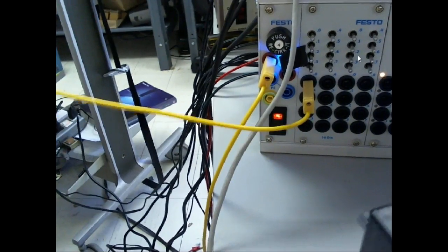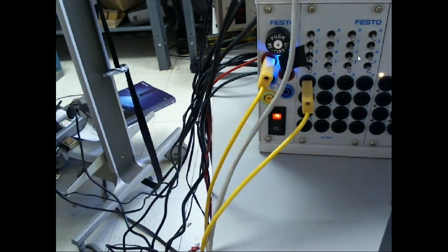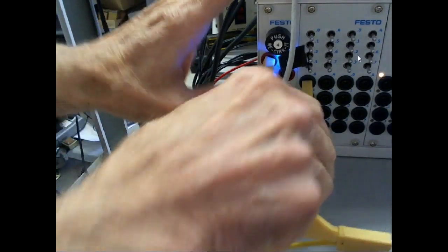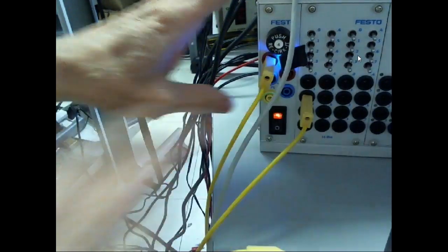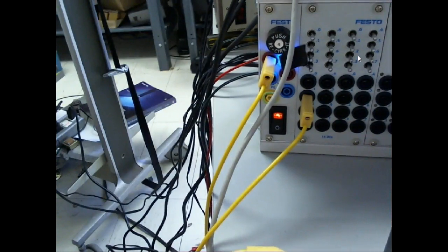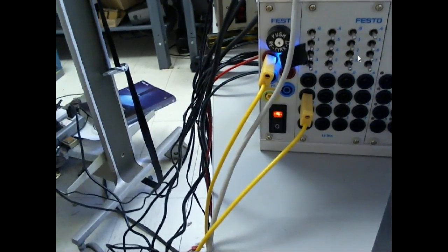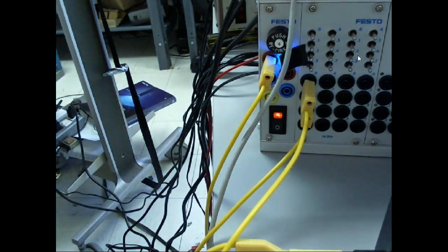So I got my normally closed hooked up to input, with my normally closed on input 0. I think it was on input 1. And then I'll take a normally open and hook it up to input 0. And these wires, instead of running to this jumper, they would run up to those ports, and you screw them down on the PLC. Okay, is everybody okay? Yes or no?